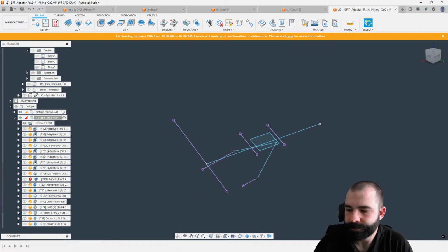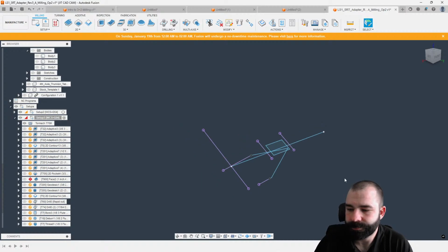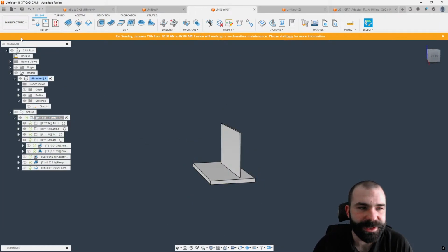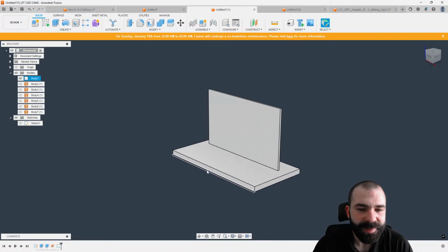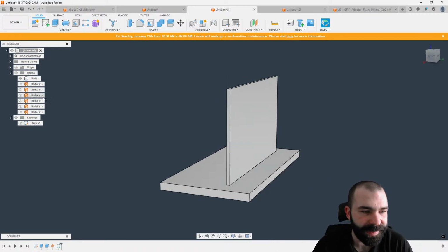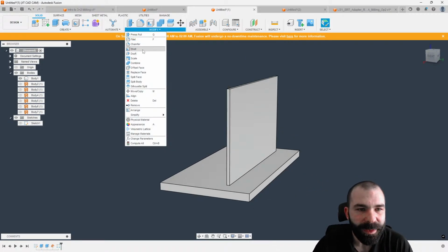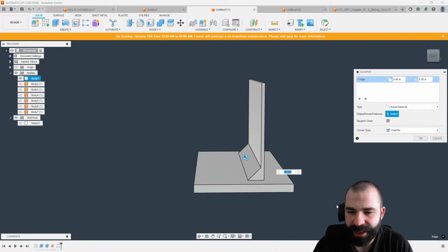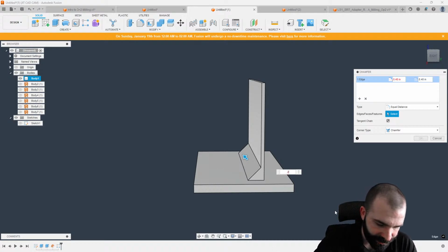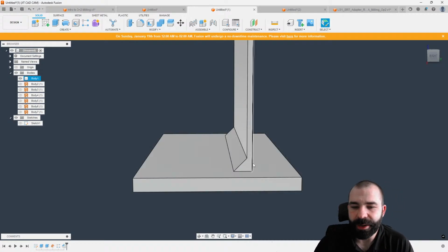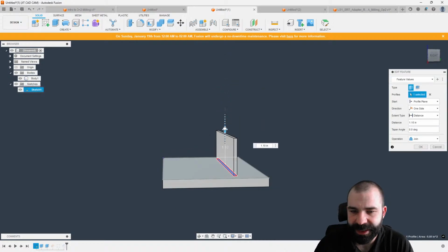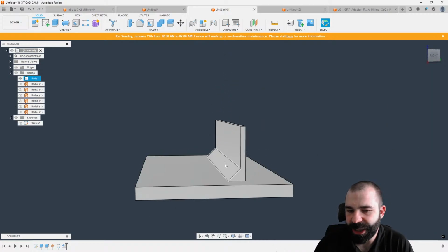Yep, I figured as much that was your question. I am going to reuse this part for what is being asked. As you can see here, we have this terrible drawing that somebody made. In the event that I had a chamfer back here on this back side, we're going to have to be a little smart about the math here, so we're going to go 250. But a mill drill, or in this case basically just a chamfer mill inside of Fusion, is able to chamfer something that's basically against a wall, right?